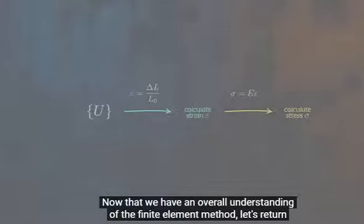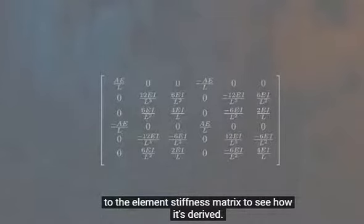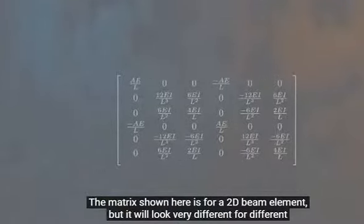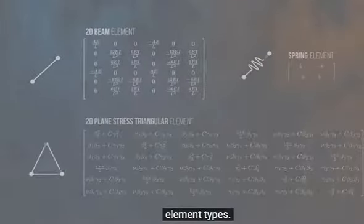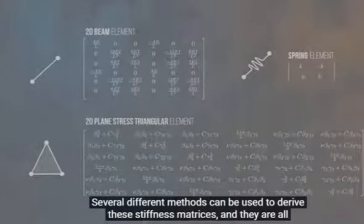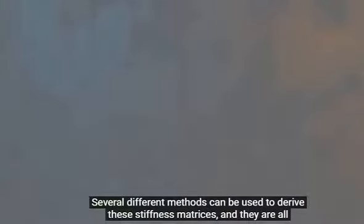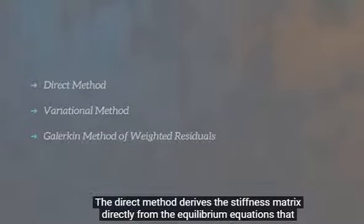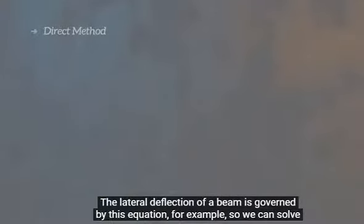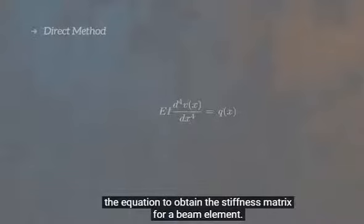Now that we have an overall understanding of the finite element method, let's return to the element stiffness matrix to see how it's derived. The matrix shown here is for a 2D beam element, but it will look very different for different element types. Several different methods can be used to derive these stiffness matrices, and they are all fundamentally based on the concept of equilibrium. The direct method derives the stiffness matrix directly from the equilibrium equations that govern the behavior of the element. The lateral deflection of a beam is governed by this equation, for example, so we can solve the equation to obtain the stiffness matrix for a beam element.